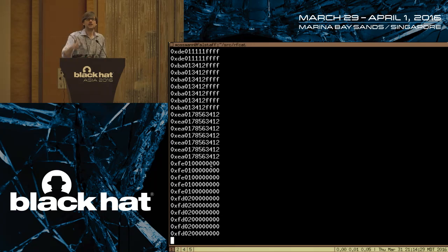Any other questions? Is this tool compatible with the RTL TV tuner? Ah, yes. The stuff that I did with the HackRF could have been done with the RTL-SDR dongle. The things that I did with RFCAT cannot be done with the RTL-SDR dongle. And that's in the category of maybe in the future we can make better tools for SDR reversing. We could make something like RFCAT built on top of an SDR platform instead of a wireless IC platform. That's totally possible. It's just nobody's done it yet.